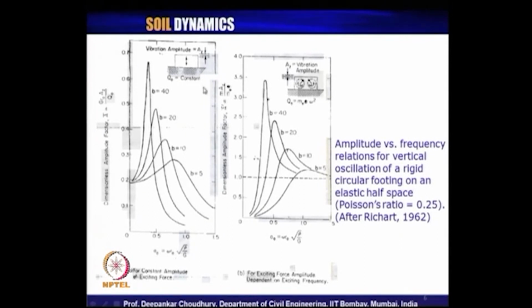So, you go to this chart for constant force type vibration, vertical mode of vibration, you can get these coefficients, and once you know g r naught by q naught, this term, you can calculate the vertical amplitude A z also. So, that is the use of this design chart, which takes care of that f 1 and f 2.